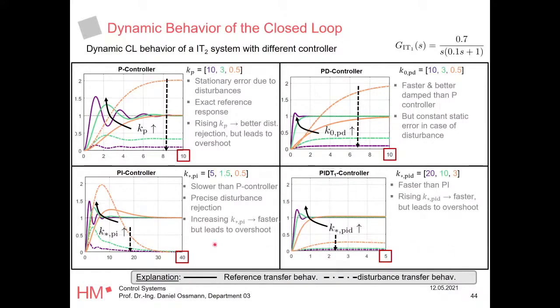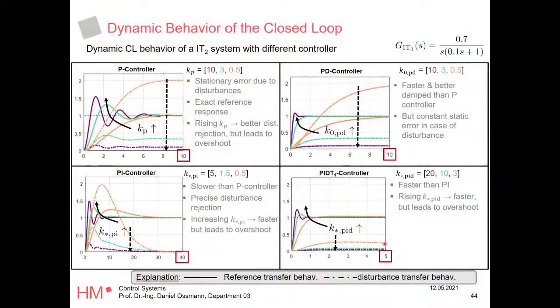So you could add another 0 here that would improve, but then we are out of the scope of PID controllers, and I really wanted to stay in the space of PID controllers, because PID controllers really do a good job very often, and when you start doing control, to understand what a PID controller and its sub-elements are doing is already enough, right? So if you want to still accelerate this, you can think of other methods which we're going to learn later, but yeah. Okay,